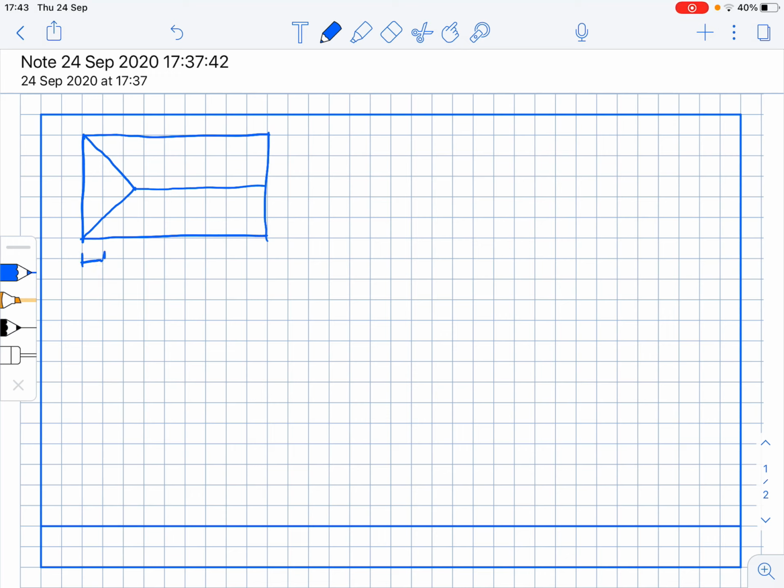Now, if this was squared paper, normally these squares would be 5 millimeters apart, and we know that 5 millimeters equals 1 meter, which equals 1000 millimeters. So we're drawing to scale. So 1 millimeter equals a fifth of this, which is 200 millimeters. So every meter I draw on this, or millimeter or inch or anything, would be 200 times bigger in real life. So we call this a scale of 1 to 200.